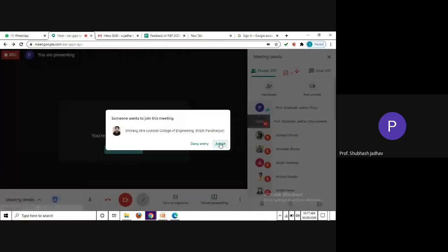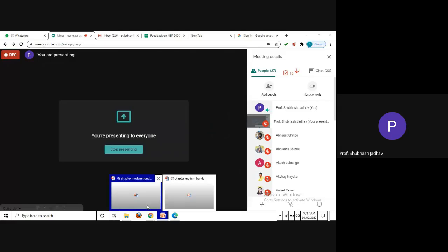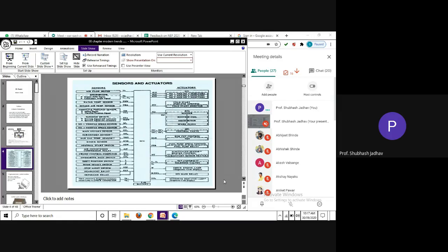So when all these particular sensors sense something, they are going to give some data to the ECU, and here it is mentioned what data is being given. The airflow meter sensor gives the velocity. Here, these particular sensors give the CO value, the NOx value, the CO2, that is carbon dioxide, or whatever values are there. Then the water temperature meter gives some temperature. Then the intake air temperature also gives a temperature. So all those values are given to the ECU.